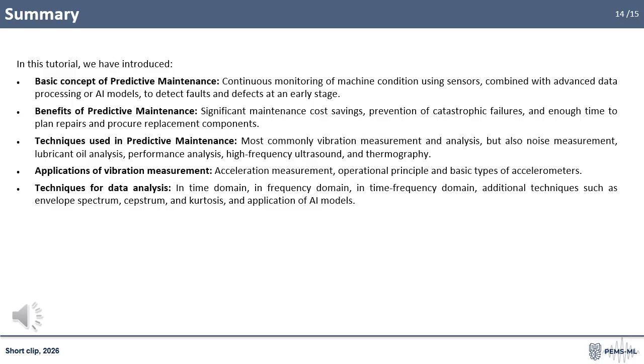Finally, we covered vibration measurement in more detail, including acceleration measurement, the operating principle, and basic types of accelerometers, as well as data analysis techniques in the time, frequency, and time-frequency domains, additional methods such as envelope spectrum, cepstrum, and kurtosis, and the application of AI models.